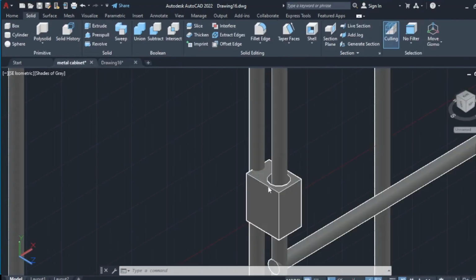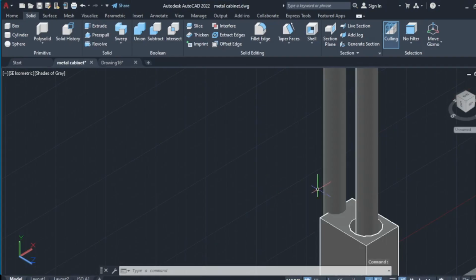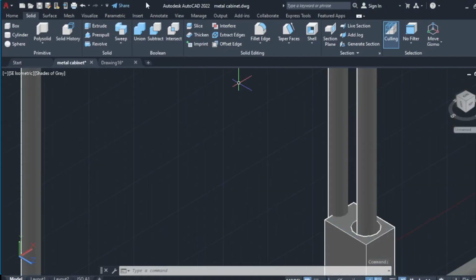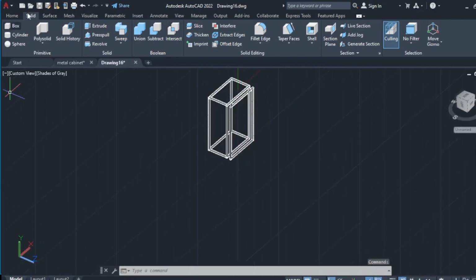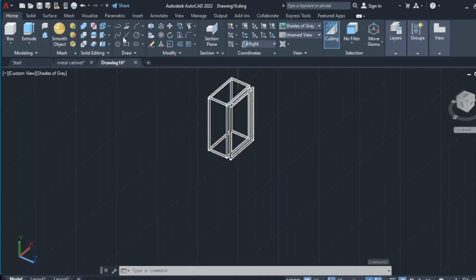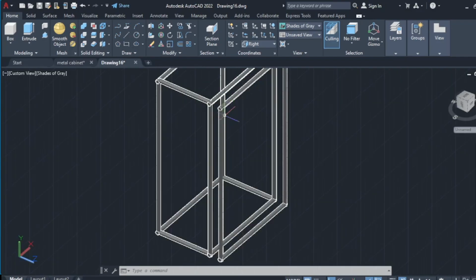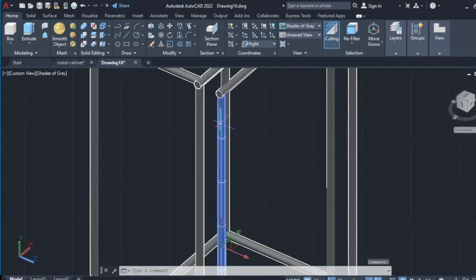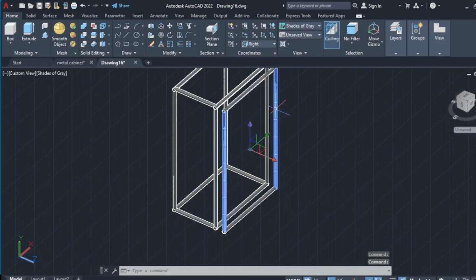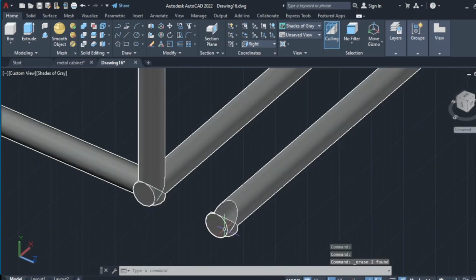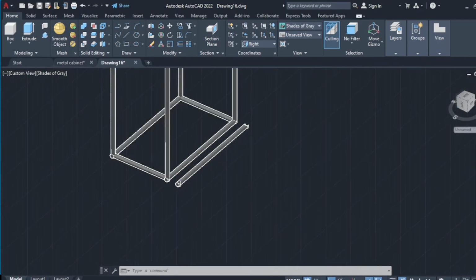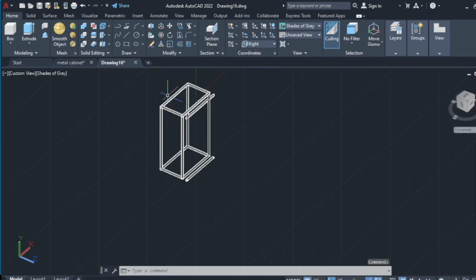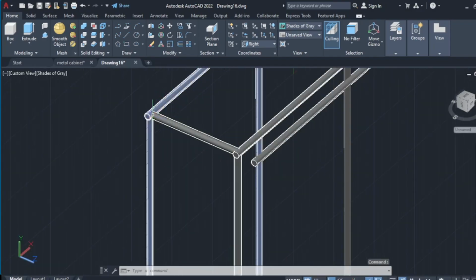So now we are designing the hinge. Let's get back to the drawing. To design the hinge, we are going to first delete this. I'm going to delete these two and make another one. The reason we deleted those two is because, if you remember in the beginning of this video, we were using press pull to extend the length of the rod.